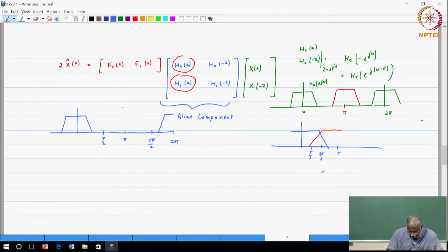Now, in order for you to actually construct the subband signal, this filter has to be of this type, right. It has to overlap, it has to pick up all of the remaining spectrum. Okay. So, when I downsample this red signal by a factor of 2, I am going to run into severe amounts of aliasing, because this is much wider than pi by 2 and therefore, there is a penalty that I will have to pay. But right now all we are saying is between H naught and H1 they must capture all of the information, that is all the point that is being made.